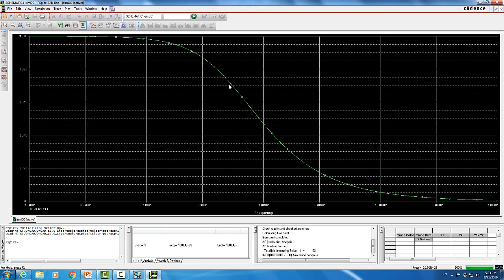So yeah, of course, because I have to do the 2 pi factor. This is in Hertz, not in radian per second. So more or less it's gonna be about 50 Hertz, right? That's the cutoff frequency. So this here is V out versus V in.